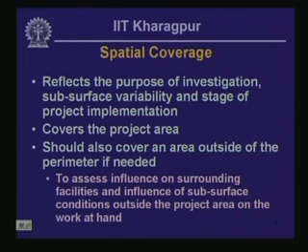If an investigation is being undertaken for a very important project, then the spatial coverage may have to extend a little bit further out of the footprint of the proposed construction, so that the effect of the proposed construction on the surrounding areas is also properly assessed during the design process.